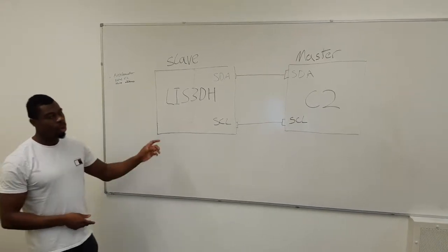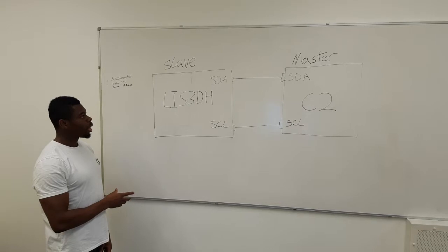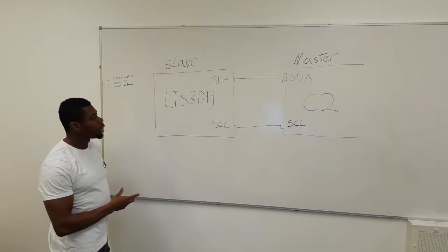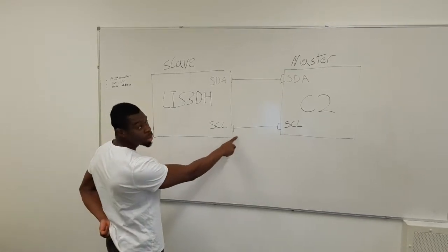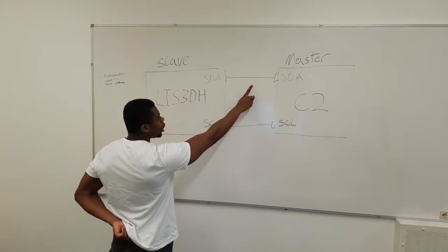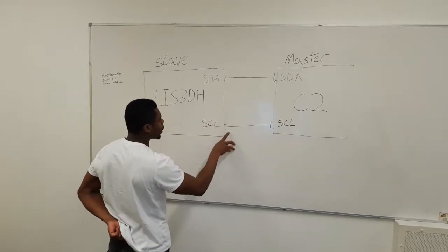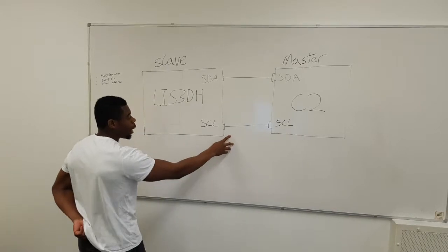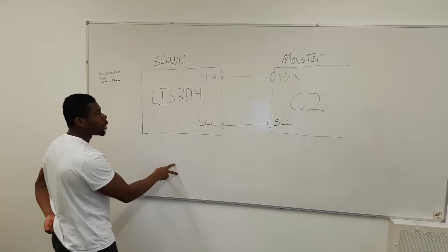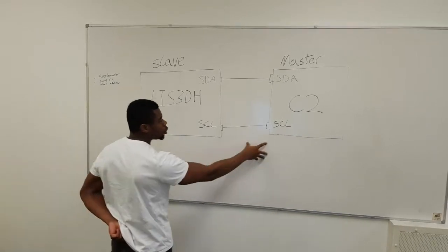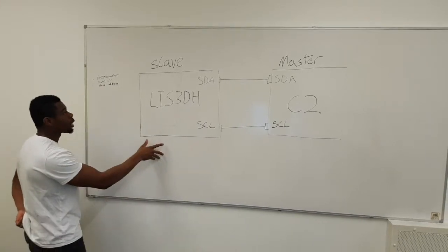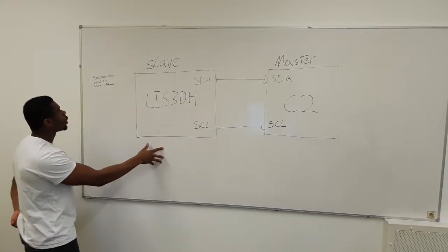So in particular, how it works is SPI communicates, it has a master and can select several slaves. So in this instance, it only uses 2 digital pins. The first transmitting data across the data line for RX and TX transmission, and then the second pin would be for a clock at the baud rate it would transmit at. Now, in this scenario, our Odroid C2 would be the master in particular, and the accelerometer would be the slave.